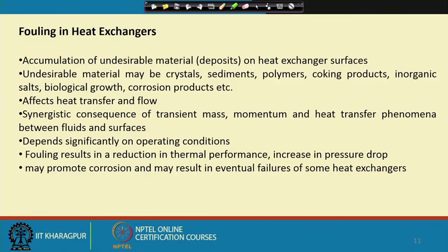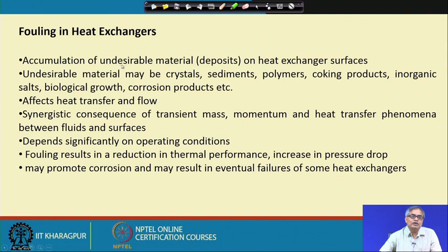So, fouling, if we go to this slide, is the accumulation of undesirable material deposits on heat exchanger surfaces. It could be on the internal surface, it could be on the external surface, it could be on the base surface, it could be on the finned passages. So, it could be everywhere. Of course, if there are two fluids, one side of the heat exchanger may be more prone to fouling, while the other side is not.